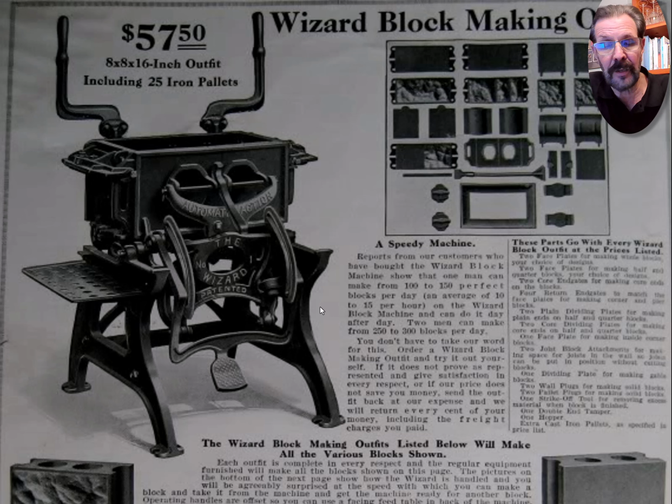So yes, this is a fancy one where you could make these blocks, but the whole idea is that you make a block with zero slump concrete, meaning only enough water for the chemical reaction. So it's such a thick concrete mix. When you fill the form with the concrete, and then you take apart the form around it and leave the block to cure, it can stand freestanding all on its own without a form right away. You don't have to wait any time. Once you've got it all in the form and it's all compacted, you pull the form away and then you can go make another one with the form. And that's still the basic principle of modern concrete masonry blocks. It's just that now they have machines that are doing this instead of people doing all of this.